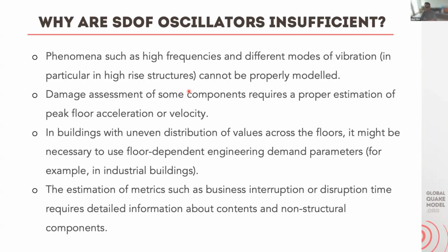The damage assessment of some components requires proper estimation of the peak floor acceleration or velocity or interstory drift, as opposed to global drift. This is also something that single degree of freedom systems can give you, these metrics, but using yet more approximations. And that's what we're trying to avoid.